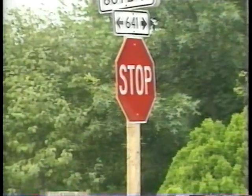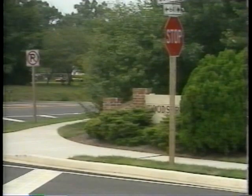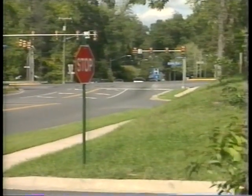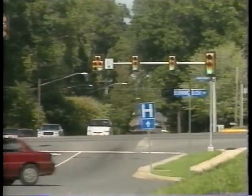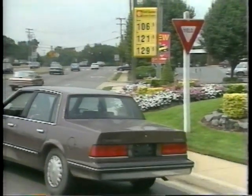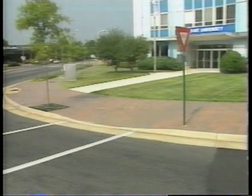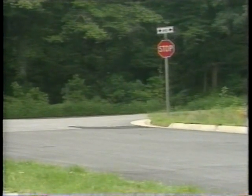A stop sign should be put at the point where the vehicle is to stop or as near to there as possible. Stop signs are used for unsignalized intersections in a signalized area. A yield sign should be put where the vehicle is to stop, if necessary, to yield the right-of-way. If there is a marked crosswalk, these signs should be put 1.2 meters in advance of the crosswalk line nearest the approaching traffic. If there will be only one sign at the intersection, it should be on the right-hand side.